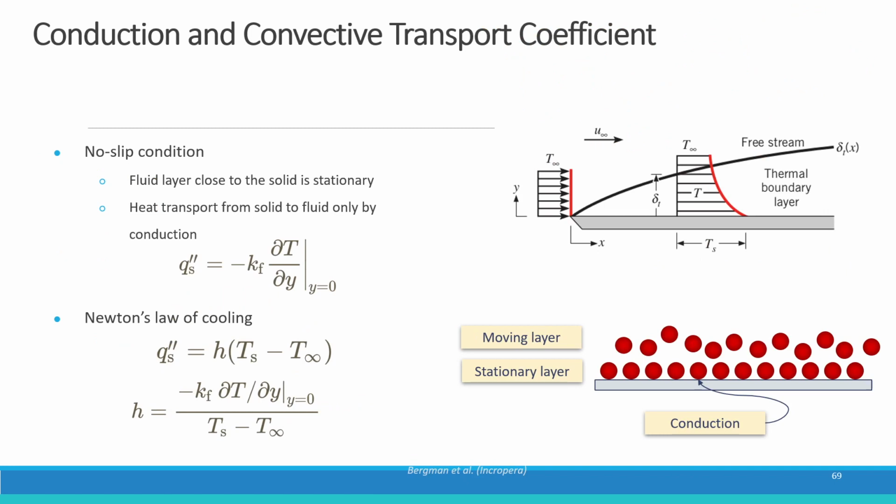In the case of heat transfer, that is for the conduction and convection phenomena that occur over this flat plate or over any given surface, at this boundary we can write the heat conduction, that is the heat flux, as q double dash equal to minus k del T by del y, where del T by del y is the gradient at the surface, that is where y equal to 0. So this was our y direction. Over here y is equal to 0, so we can write the heat flux depending on this temperature gradient at y equal to 0.